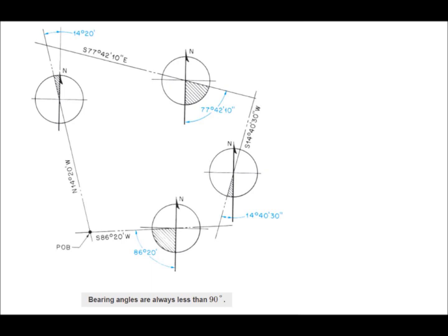The point of beginning may or may not be shown on the site plan. If the point of beginning is not shown on the plan, start at a convenient corner. Corners are usually marked with a pin, IP, or some permanent feature. The approximate direction of the boundaries can be found with a handheld compass. This approximation should be accurate enough to aid in finding the marker at the next corner. Proceed around the perimeter in this manner to find all corners. All construction activity and debris should be kept within the property boundaries unless permission is first obtained from neighboring landowners.